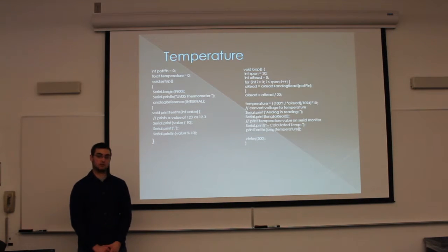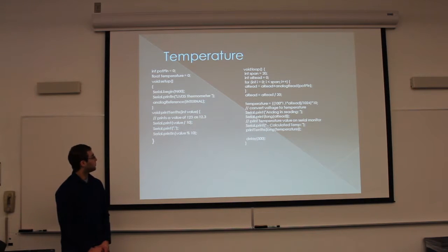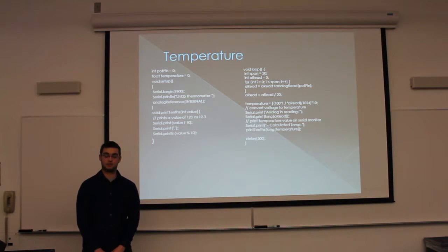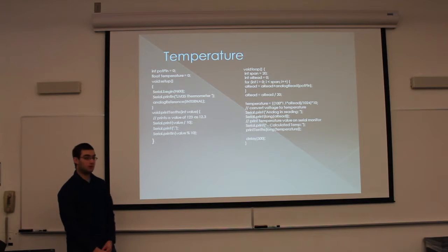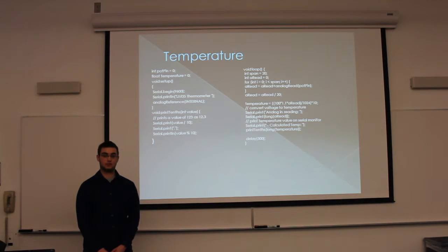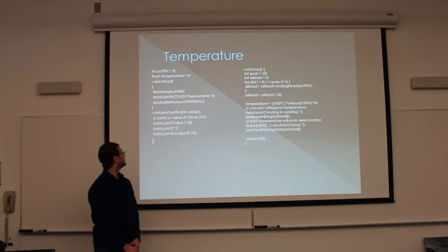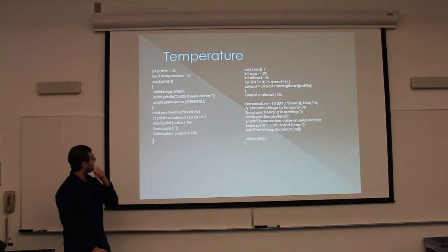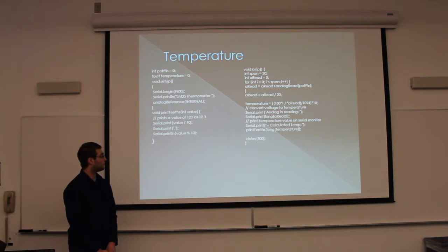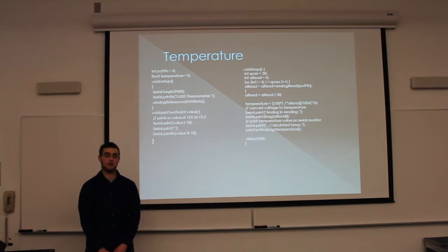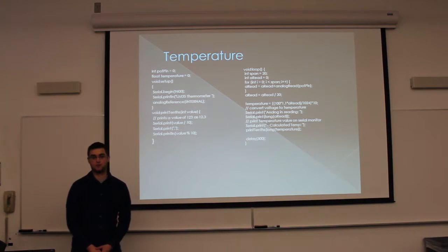There's not much setup. In the serial port, it just prints out the thermometer, and the LM35 is the name of the actual sensor that we're using in order to measure the temperature reading. Then the analog reference internal makes it so that it references the internal reference, pretty self-explanatory. Then what we have after that is a function, printTenths, and what this does, as it's called later, is it prints a value of 123 as 12.3, and this is because the temperature reader obviously does not read just in degrees Fahrenheit.